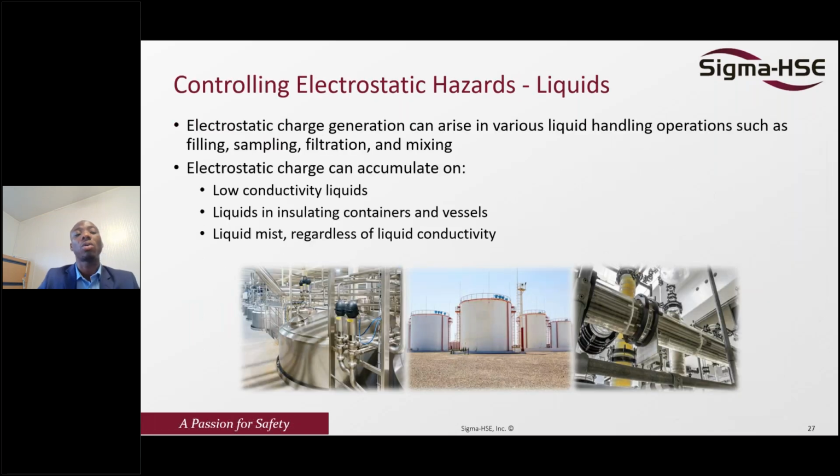So how about controlling electrostatic hazard for liquid? Electrostatic charge generation can arise in various liquid handling operations, such as filling, sampling, filtration, and mixing. That is something very, very common in the industry. And depending on the conductivity of the materials, it can create a significant amount of charge that could discharge.